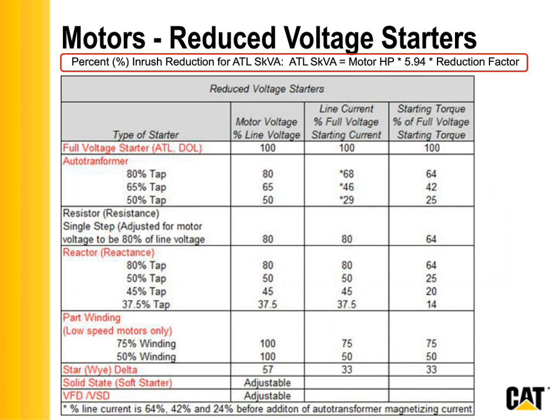What we're talking about here is tools and tips that you can use in SpecSizer to help you reduce your sized genset. Remember, we started talking about running kW and kVA and duty point percent, and that's the only thing that you can do to reduce your running. And we also talked about inrush. What are the things that you can do to reduce your inrush or your starting kW and your starting kVA? There's something called reduced voltage starters. You find this on your 3-phase motor dialog.